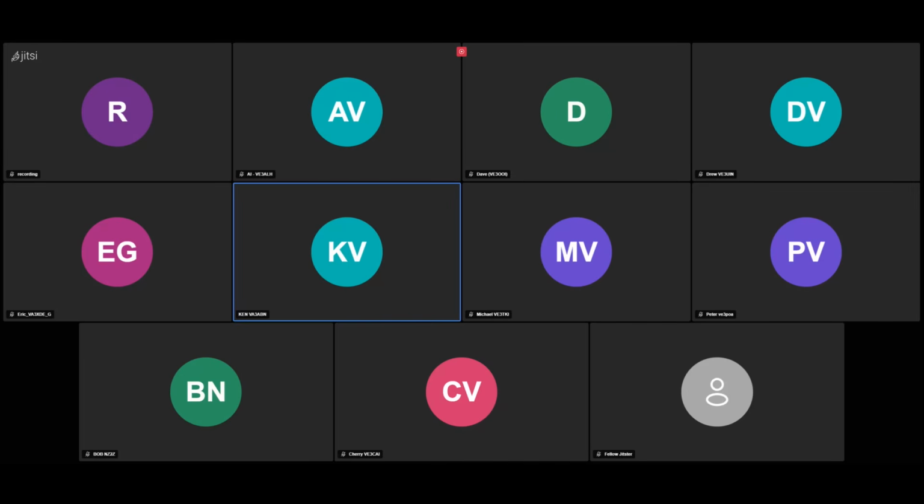From 40 to 10, I was under 2 to 1 without a tuner, and that was using a 4 to 1 balun. But I think I've got enough information and screen grabs and everything. I might try and put a presentation together and do a presentation about it later on. I plan to continue working with this.